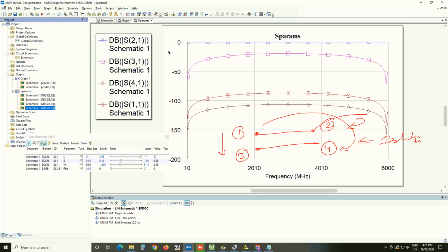But that's why it's coupling minus isolation, because the coupling is also reducing the amount of power you're actually measuring, right? Original power is 1. Wanted power is 0.01. And then there is some unwanted power. So you have to compare the unwanted power with the wanted power, which is already small compared to the original signals.